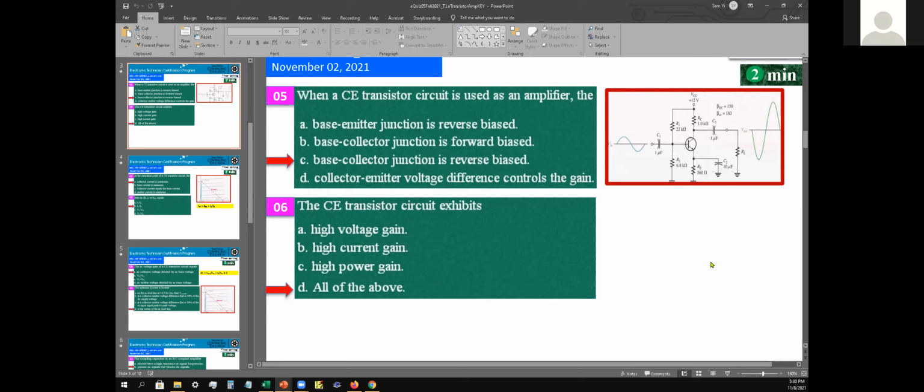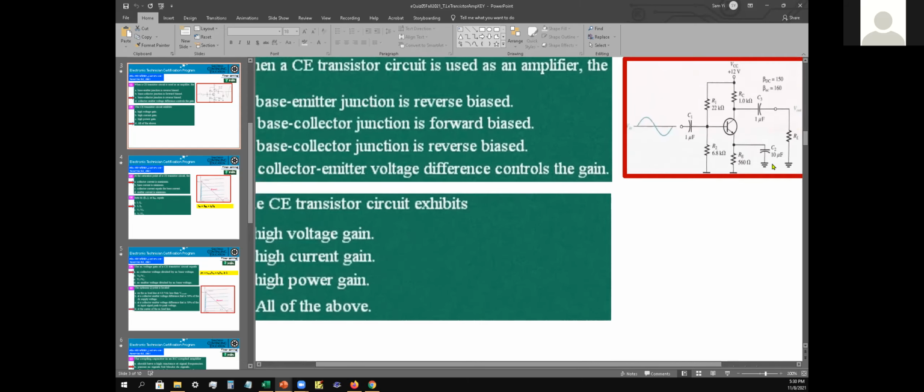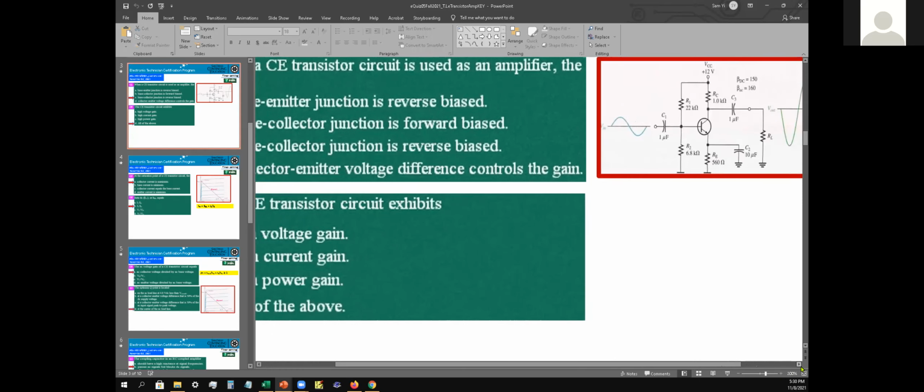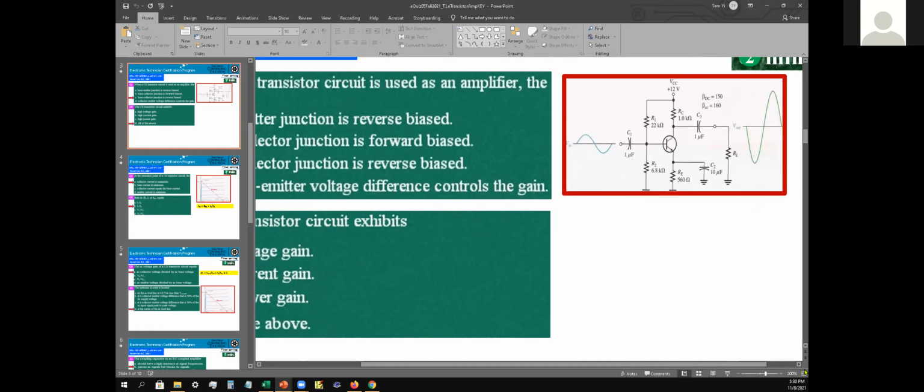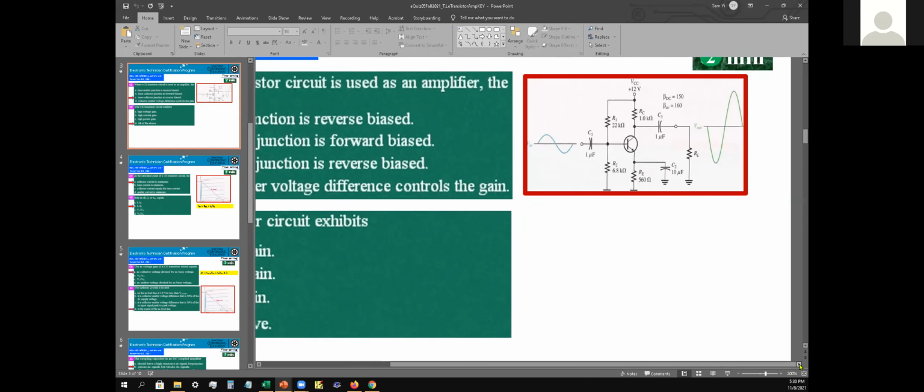Right. So C1 and what's that? C3. The current is only going one way, but that's being blocked. Yeah, that's C1 and C3. So technically, at C3, the direction for DC is going right. The DC would be flowing through this way to bias the transistor, but it does not have to deal with anything about the output. The output is only the AC signal that goes through the capacitor.